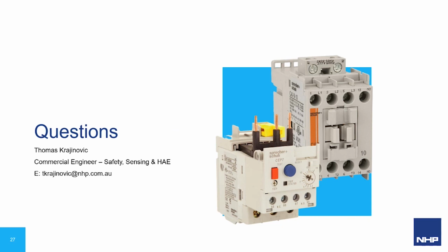So we've got another one here. It's not a bad one. So do we always use the cold trip curve for the overload chart? Are you able to answer that, Tom? Yeah, so you do have to, especially for EXE, as we went through, because you need to look at the current and the stopping time to make sure that in that situation where you're at the locked rotor current, at that time, you need to ensure that the motor stops.